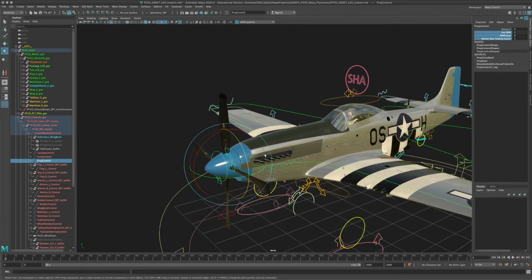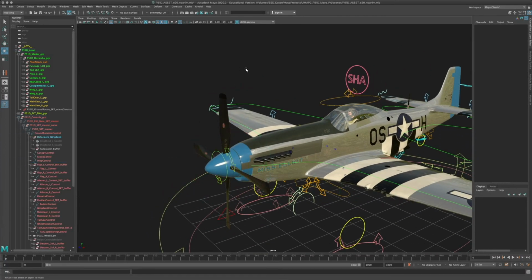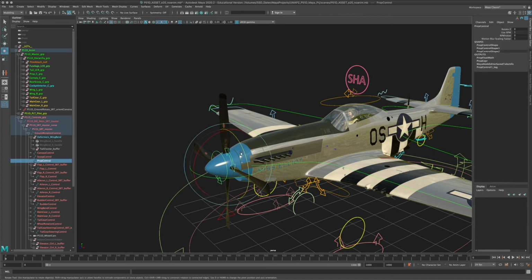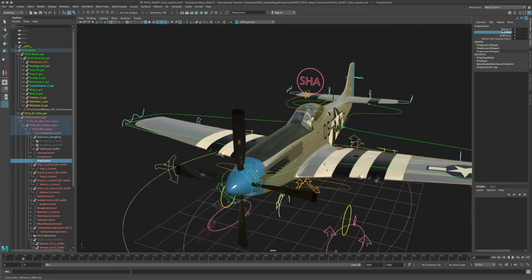When animating a plane or such a kind of technical object, you usually also want some kind of natural control over the plane. So the propeller also has this option here, which by default should be 0, so that's use RPM. So you can actually put in some rotations per minute value to control the propeller, which means that you can also ramp up or down this value over time, and it will start to spin up or slow down.